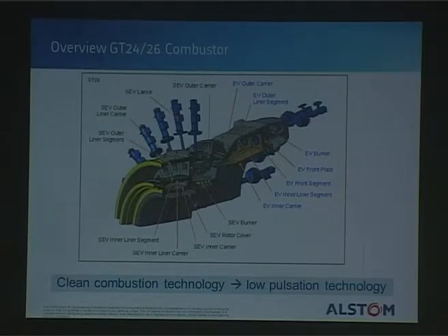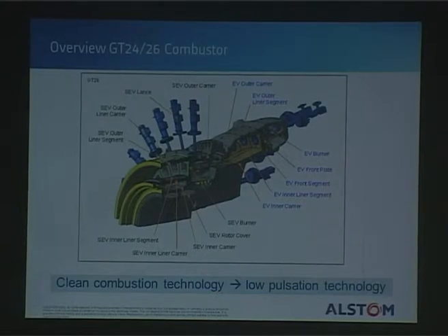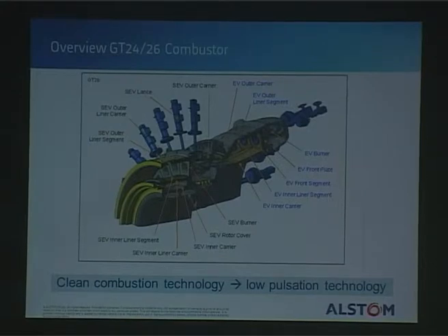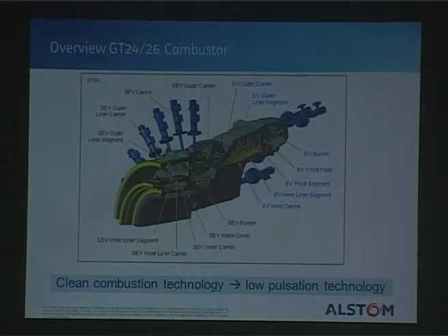When it comes to new combustion technologies, NOx emissions are a very important aspect. In essence, it's quite simple to achieve low NOx emissions, because given the amount of gas and fuel that you have, you just have to make sure you mix it very well and you have low NOx combustion. But in practice, the biggest constraint is that if you do that, you get quite high acoustic pulsations, or at least you have a big risk of getting them.